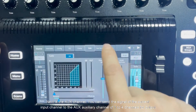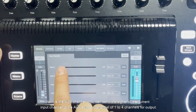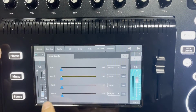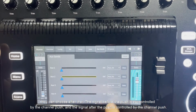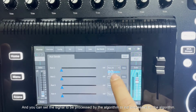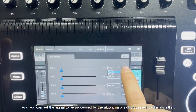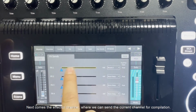Next is the AUX channel. You can send the signal of the current input channel to AUX auxiliary channels 1 to 4 for output. You can choose pre-fader or post-fader: the pre-fader signal is not controlled by the channel fader, and the post-fader signal is controlled by the channel fader. And you can set the signal to be processed by the algorithm or not processed by the algorithm. Next comes the effector channel, where we can send the current channel for processing.